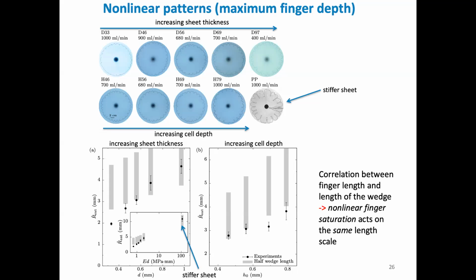And the reason why it's impossible when you're injecting at a constant flux is from simple geometry. You can imagine as your interface extends, your circumference becomes bigger and bigger and bigger. And because the flux is constant, you therefore have to slow down to accommodate the bigger and bigger area that you're occupying. So we knew that this would not work in a radial cell, but we still wanted to.